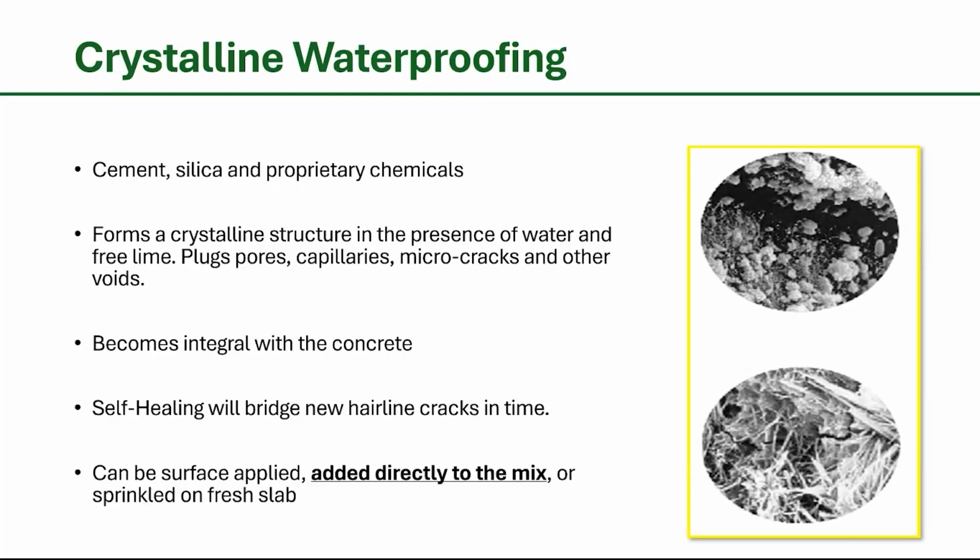Crystalline waterproofing is an interesting thing. With crystalline waterproofing, we're growing crystals of calcium silicate hydrate in the pores of the concrete. So we're adding extra calcium silicate hydrate to the concrete. If we're adding it as an admix, that would be your crystalline admixes. Cementitious works the same way, where it grows those calcium silicate hydrates. It takes time for these crystals to form. It takes up to 28 days for these to form. So it's not going to be waterproof right away, but as an admix, you can have 99% water impermeance in a slab, and it's very impressive, very useful in certain situations. But it does take time for these things to form.